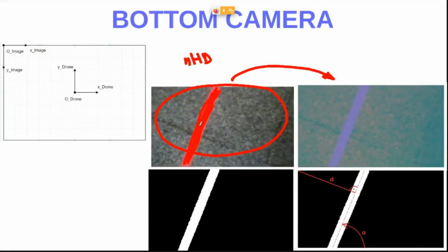Why? Because as you can see, this red line is placed just on the floor. At the end it's a red tape on the floor, and here I have from black to white. The problem is that if I take a picture with the RGB matrices, we have the light intensity for red, the light intensity for green, and the light intensity for blue, okay? Here I have a lot of colors, because I have a lot of gray intensity colors in here, and I have different combinations of RGB. So if you have a look at the R matrix, it will be so hard to find a red line, despite you think it's so easy, okay?